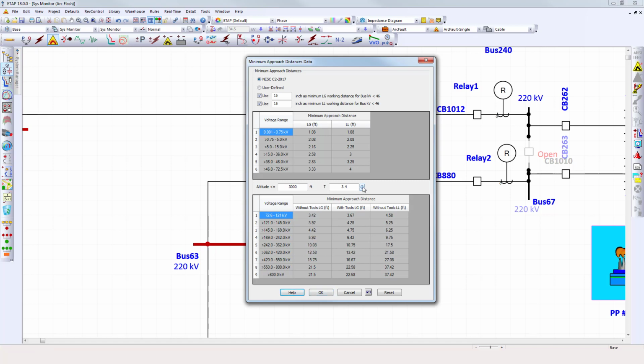And once you determine the level of over voltage conditions, which are all included within the program, you can see that these distances vary. So for lower voltage conditions, the distances are smaller or shorter. Therefore, the typical gaps and working distances will be less, and therefore the energy values will be calculated accordingly. All of this comes included with the ArcFault module and is integrated into the ArcFault calculations.